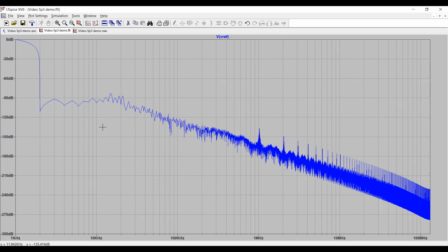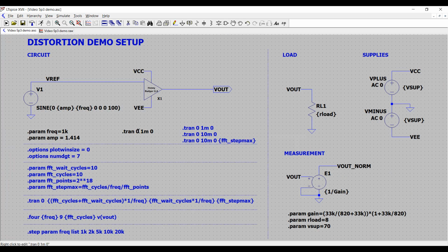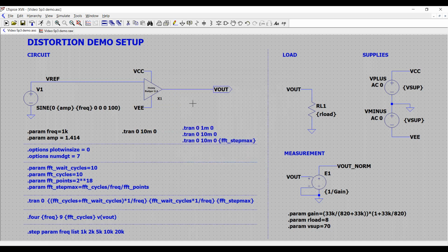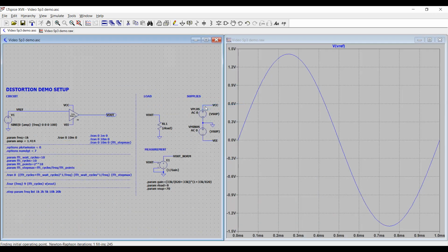So you can see why we need to actually take those considerations that I spelled out earlier quite seriously. The first thing that I'm going to do now to improve things is I'm going to sample 10 cycles. So our sample window was 1 cycle in this first iteration. Let's increase that to 10 cycles. So say OK. And I'm just going to run.